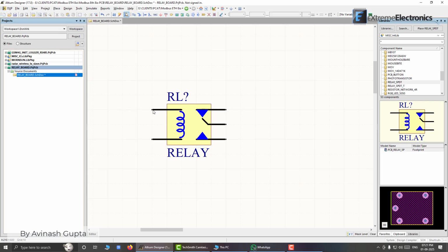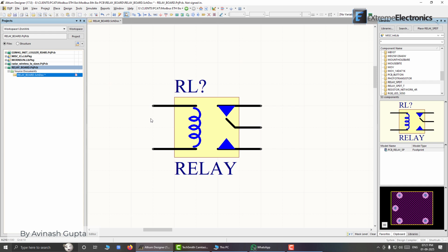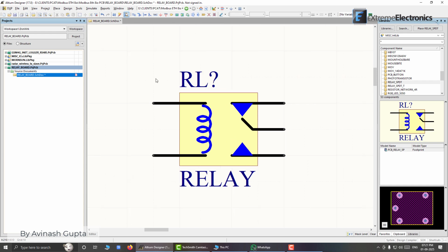These are usually placed on this 10 unit grid. So this one is here, this one is empty, and we have another here. So this is a multiple of the 10 grid. We have 0 here, 10, 20. That is why this pin should always come on the grid. Here you can see light grid lines. Pins should fall in the center of these grid lines like this. If it is off grid, you will have trouble connecting these pins.